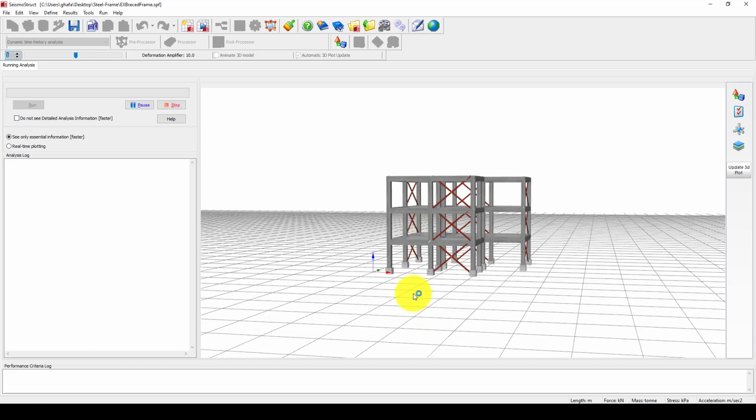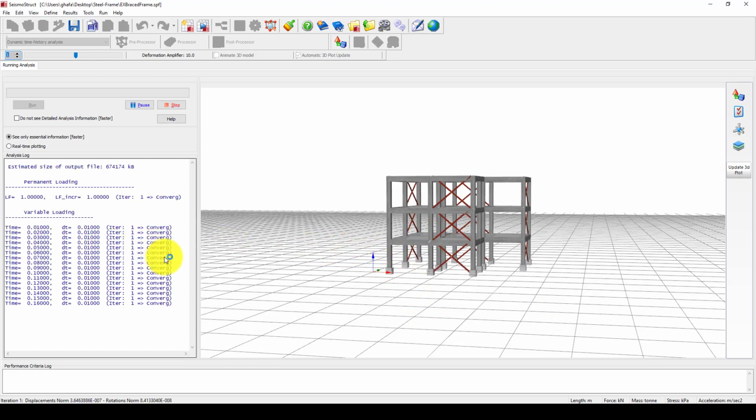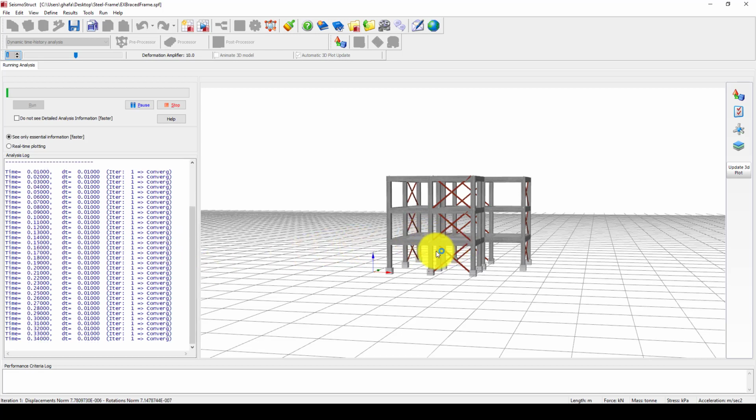So we can say yes, we want to see the convergence, because when the damage becomes very large, the program cannot converge for you. At that point there will be significant damage, because the capacity of a fixed node and also a pin node is limited. Now there is no problem until 2 seconds, almost 2 seconds. So convergence is okay. It takes a while to finish 40 seconds. After it finishes, we will see the result and interpret it.